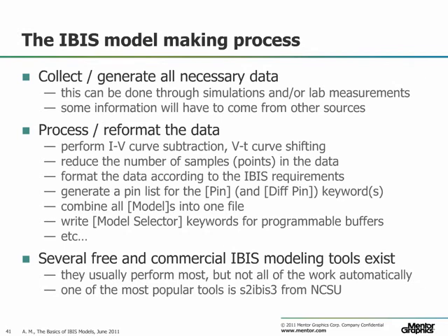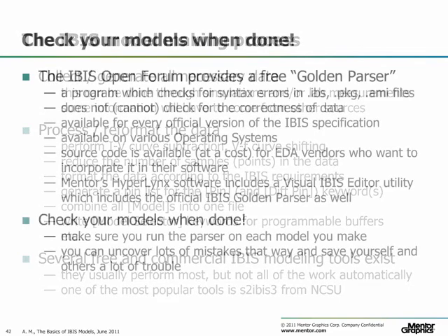Once you have collected all the data, you'll have to do some processing and formatting to conform to the IBIS requirements and rules. This could be a tedious job if it had to be done manually. Fortunately, there are several free and commercially available IBIS modeling tools, but to my knowledge, none of them achieved 100% automation for the model making process.